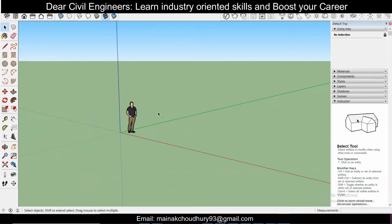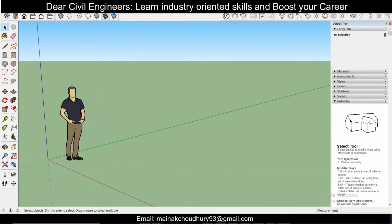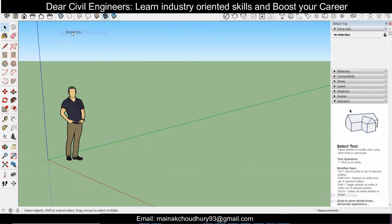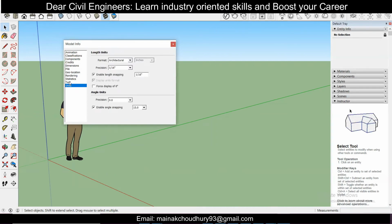The first thing which you need to do is the unit setup. For the unit setup, you can go to the Window option and then Model Info, and then you have different options, and there you have the option of unit setup. You can just use architectural and precision. You can increase this similar to AutoCAD, 1/16, 1/32, whatever you want.